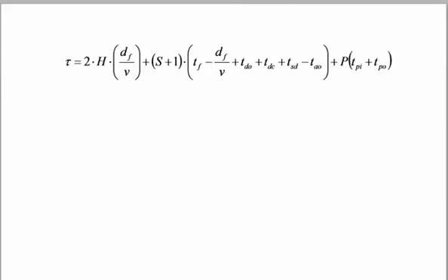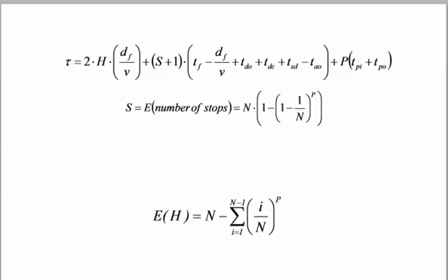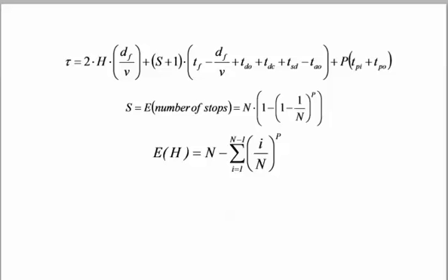And if you look here, for example, you would see these three equations, very widely used, they've been around for a long time, and these are the three classical equations that form the basis for calculating the round-trip time. The first equation shows us how to calculate the round-trip time, which I've denoted here as tau. The second equation tells us about the expected number of stops, and the third equation tells us about the highest reversal floor. Combining all these three equations, we can arrive at a value for the round-trip time.